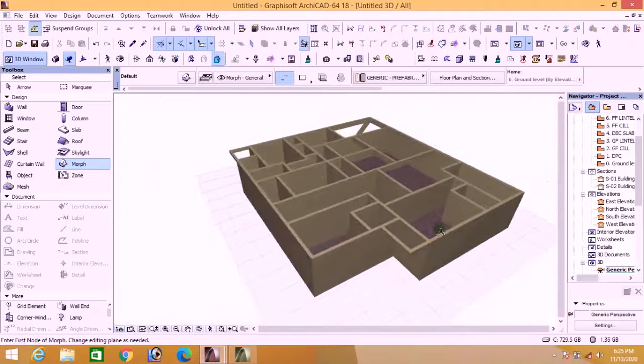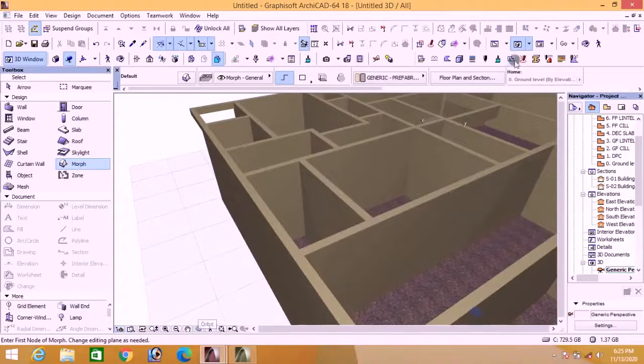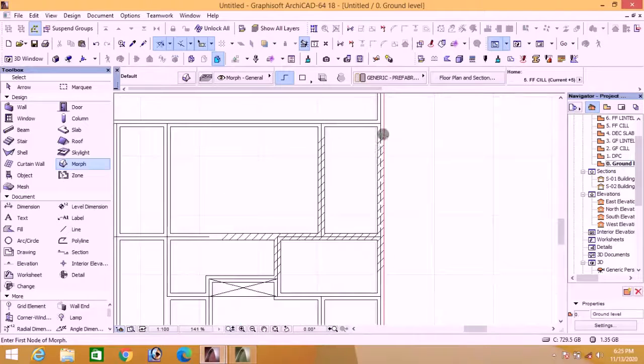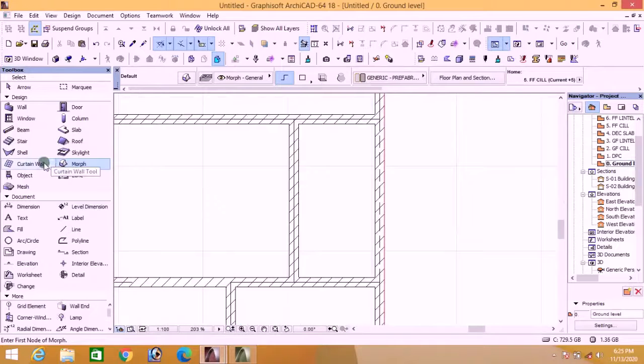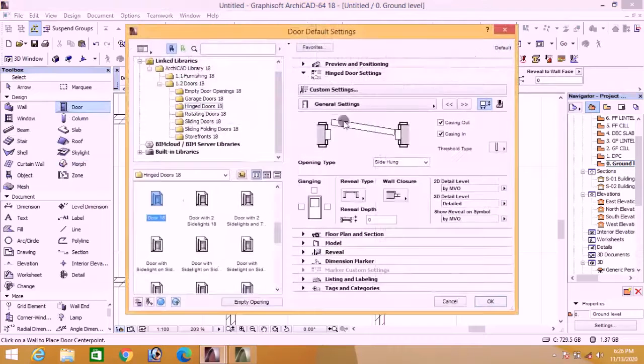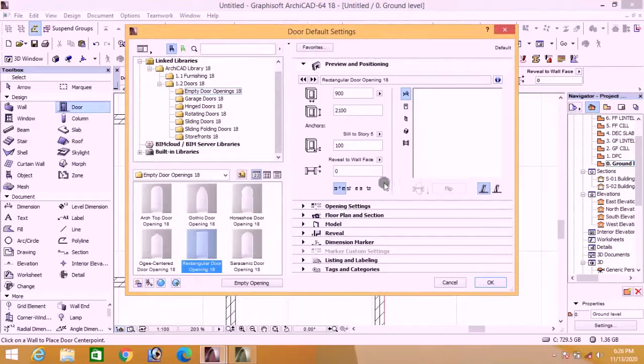Now, having installed the beams that are supposed to be in their positions, another place we install a beam is here. We have a beam line here, but to do this we have to use the normal wall setting opening. So click on your door, click at this spot, go to empty opening and click on this spot, and click on 0. When that's done, click OK.